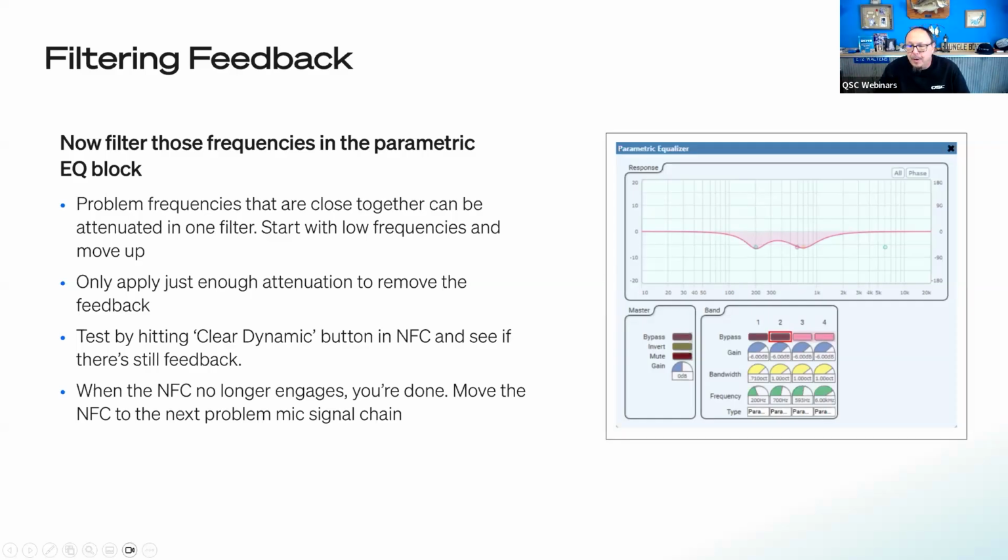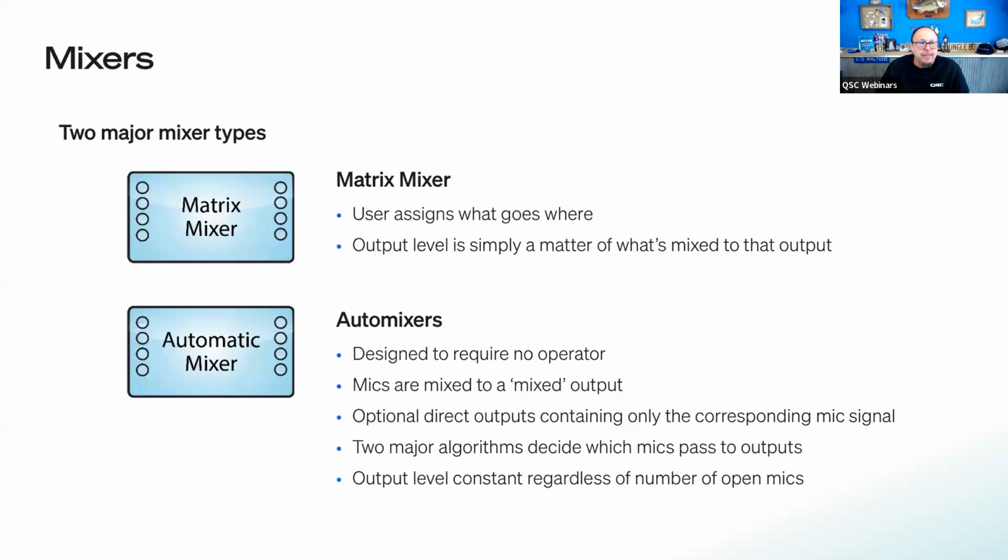Now, one thing to remember, these do engage level 2 memory usage, which is also AEC, and also reserves that memory usage as well. So if you have 20 mics, don't put 20 notch feedback controllers in. Put it in your test tools or something like that, and just go through and use one to set up all your mics and then move forwards. All right, let me keep moving along here.